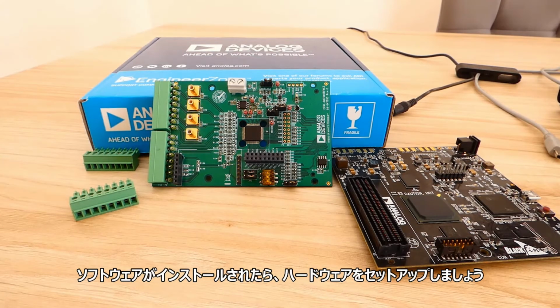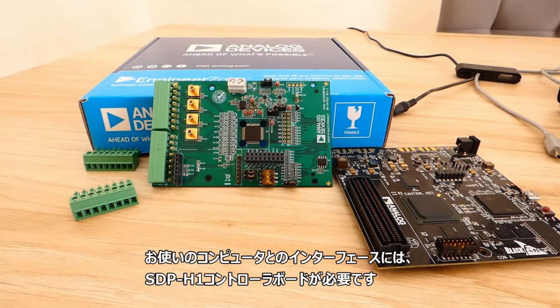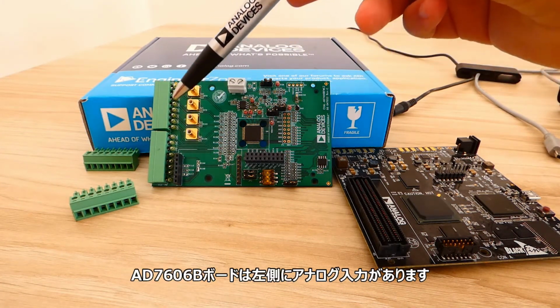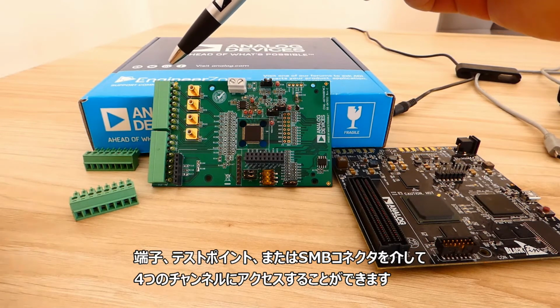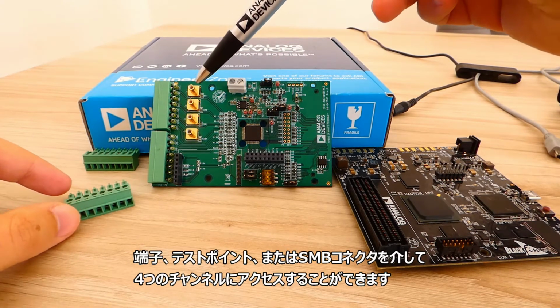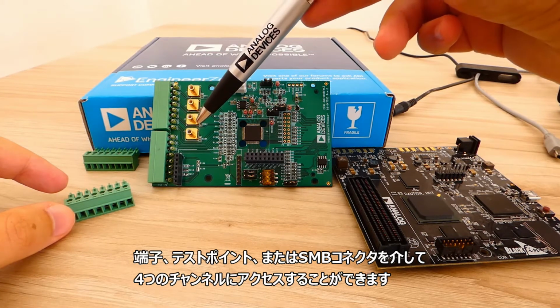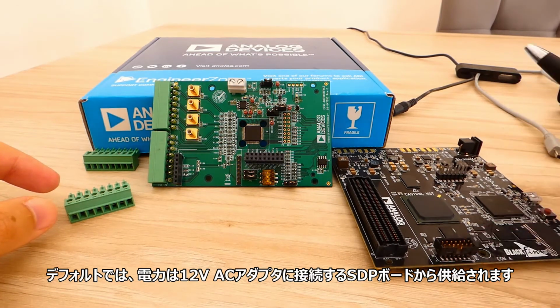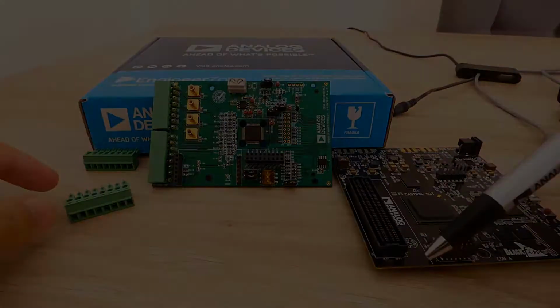Once the software is installed, let's set up the hardware. Note, you will need an SDPH1 controller board in order to interface with your computer. The AD7606B board has the analog inputs on the left-hand side. These can be accessed through the terminals, the test points, or, on 4 of the channels, through the SMB connectors. The power, by default, is supplied by the SDP board that connects to the 12 volt wall adapter.